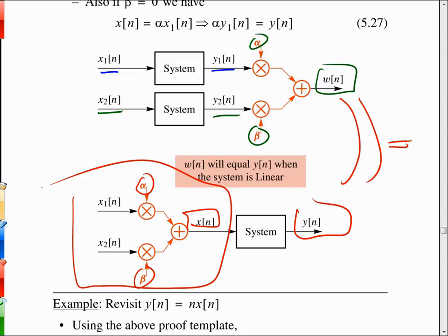And the linearity idea is, I could say it's awesome and you wouldn't believe me, but it's what makes everything work. We can superimpose signals. And why do we like to superimpose signals? It's because we model something with just one signal applied. We fully understand that, then we model it with another signal applied, then we say if the system is linear, we can just bring them together, and we already know what the response is going to be because it's just going to be the sum of the outputs. We don't have to do our initial analysis. And in circuit modeling, that's exactly what you do.